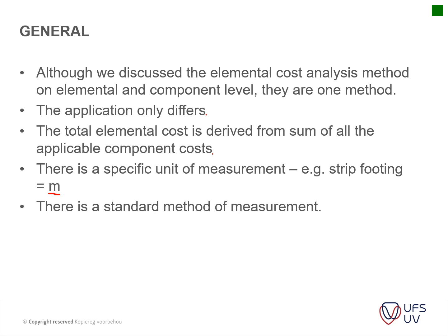So that is something that you need to remember: your elemental estimation groups an item like strip footing into one, whereas your bills of quantities actually breaks it down even further. Okay, so I don't want to go into it too much, but you will see later on in the presentation how that works. There's a standard method of measurement. This is very important, and I'll still share the standard measurement system with you that you can use when you do your task.